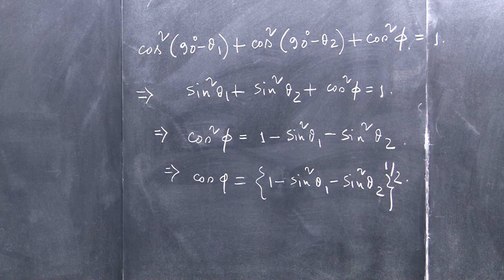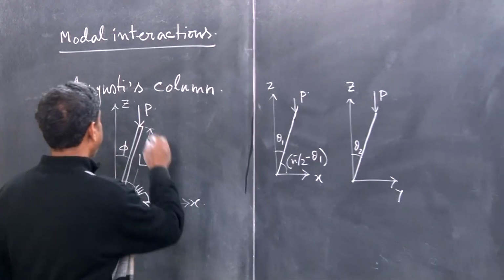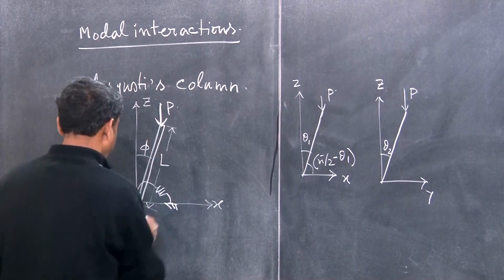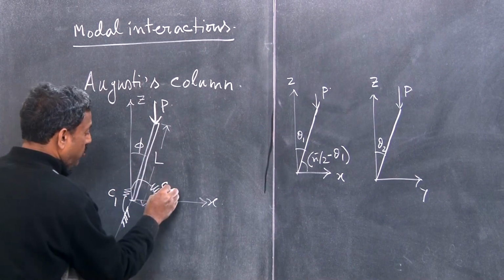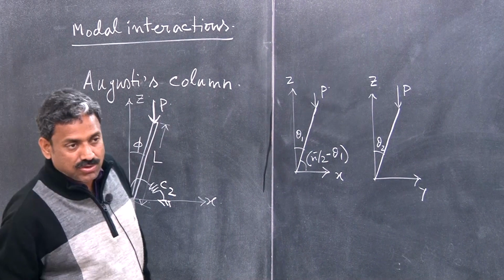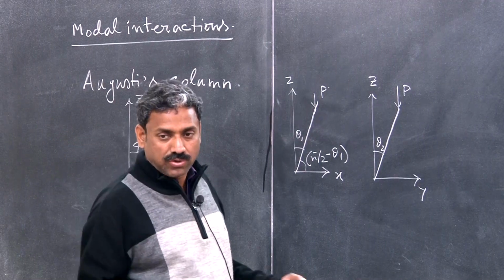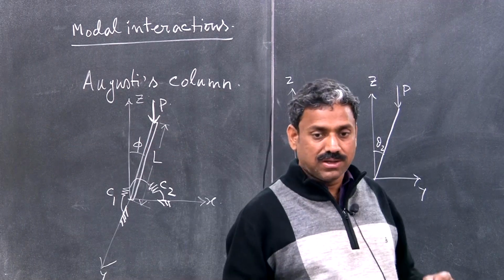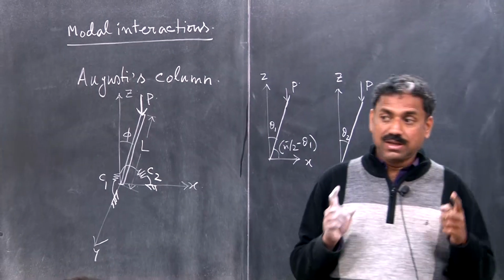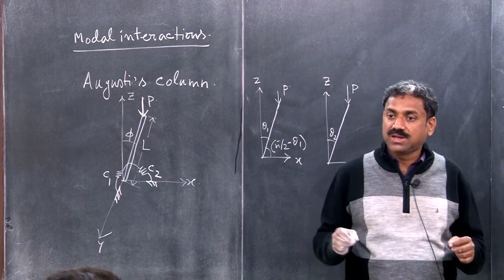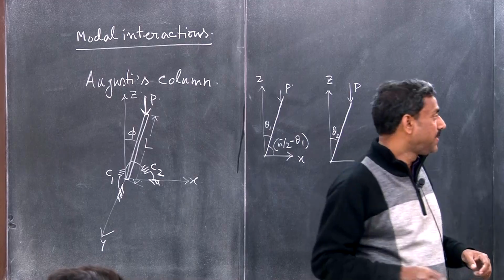You understand what I am trying to do, right? I am assuming this is C1, this is a rotational spring. Why are we using a rotational spring? Because we know that a rigid bar restrained by a rotational spring has stable bifurcation, so that is imperfection insensitive, right?